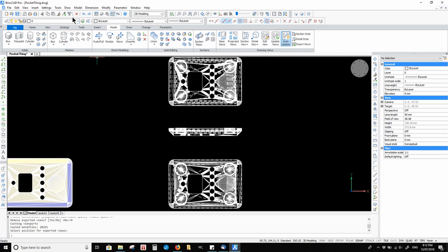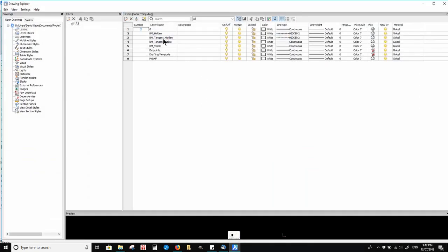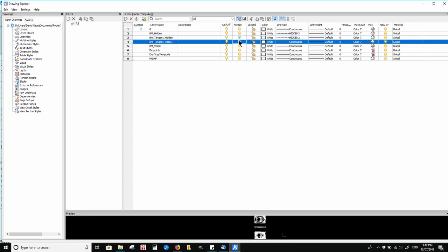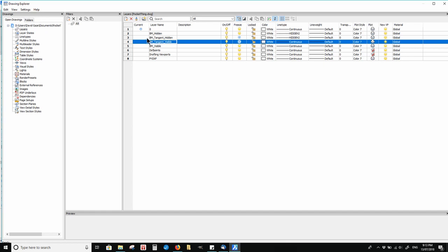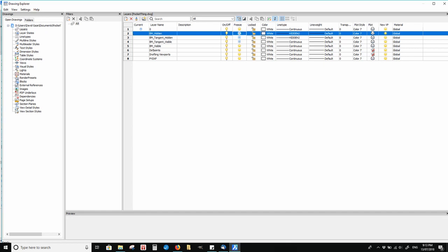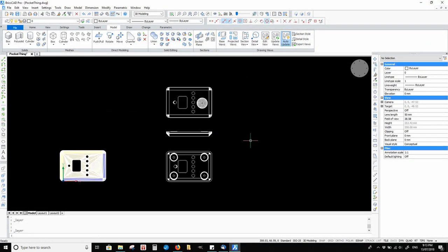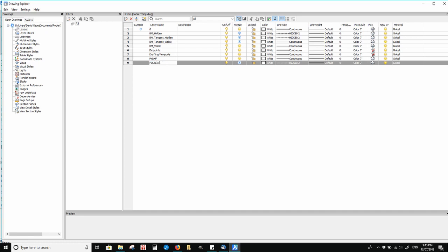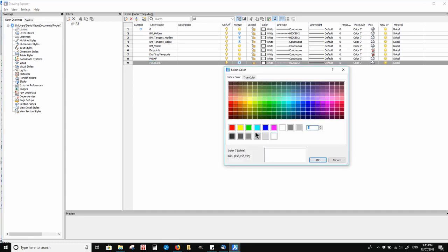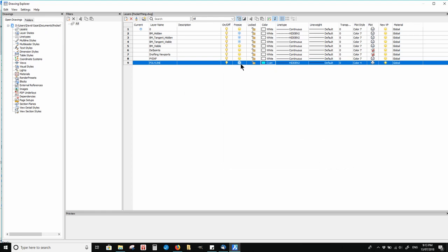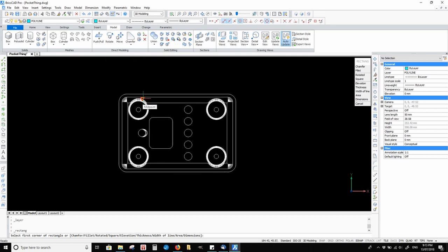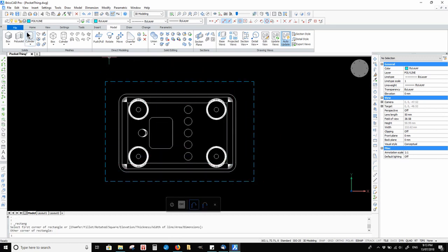It looks like a mess of lines. Turn off the tangent, hidden tangent, and hidden layers. Make a new layer for your drawings. Now we are going to use what artists call negative space to create our outlines to begin with. Put a rectangle around the bottom view.